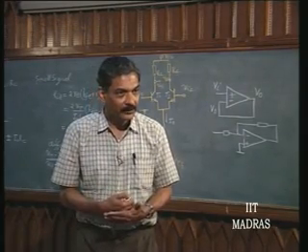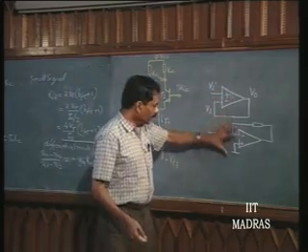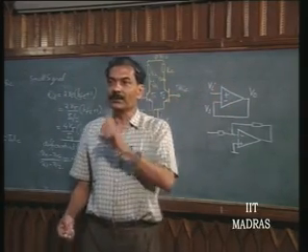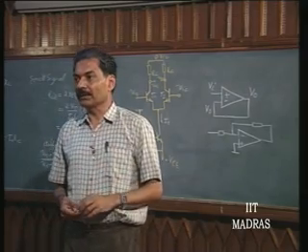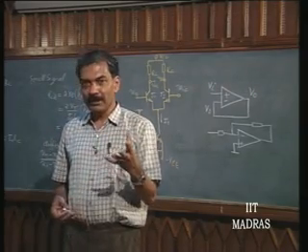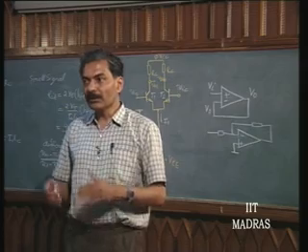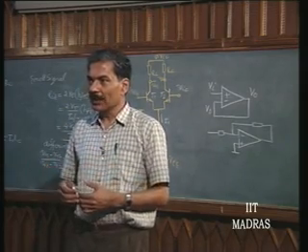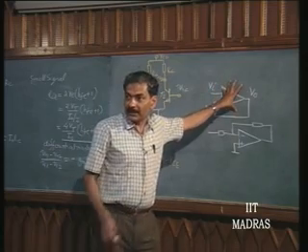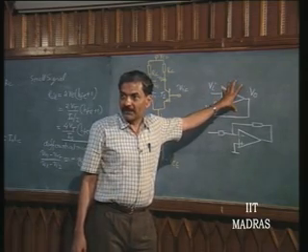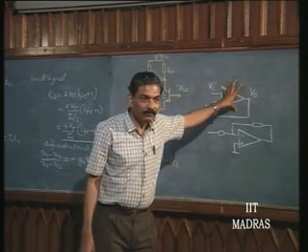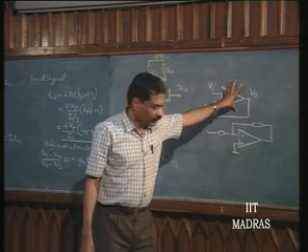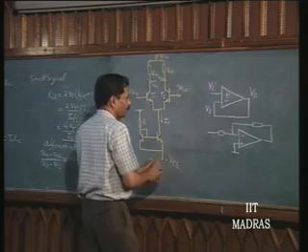This point is clear. So, these are clear examples where you, as a design engineer, should know how to design an op amp given its application. Where is it most likely to be used? If it is going to be a general purpose op amp which is going to be used in any mode, then you would design it for the worst case. And the worst case is the maximum negative feedback situation, that is called the buffer stage. So, please bear this situation in mind.